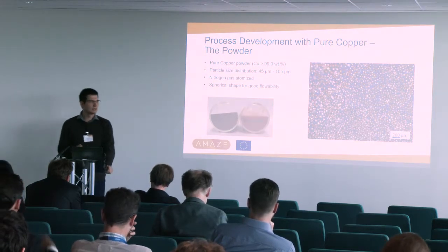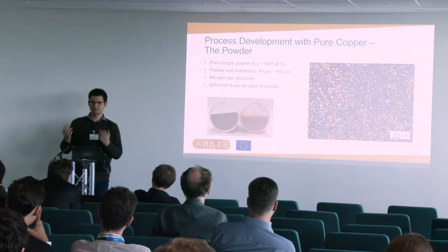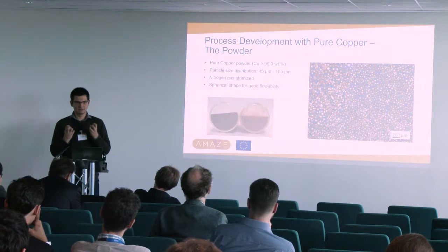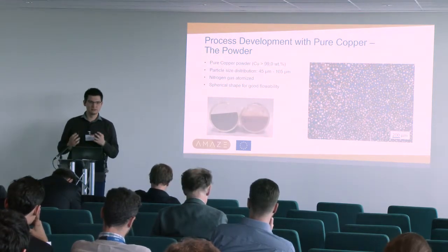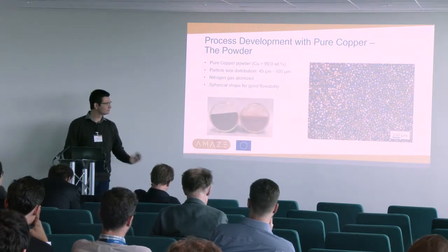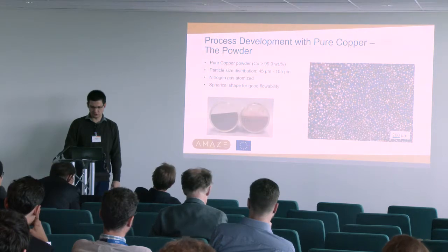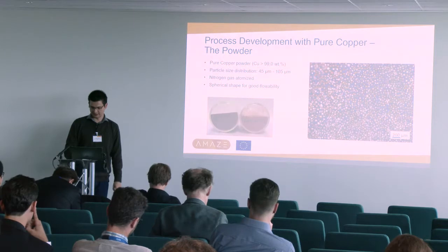That means for weldability, normally someone would put in phosphorus to bind the oxides, but this is not good when you use it in additive manufacturing. You don't need that. So if you ever order powder, make sure that it's free of phosphorus and has a very, very little oxide level.